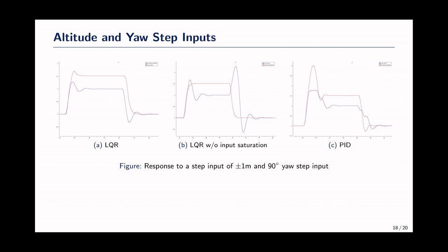The yaw one has an interesting stair step approach, and you'll notice that happens at the same time that we're trying to yaw. It shows that the 2 controls are fighting each other, since as you yaw, you have to speed up some motors, and so you end up moving faster than you'd like. And so you get this stair step where your controls are fighting each other.